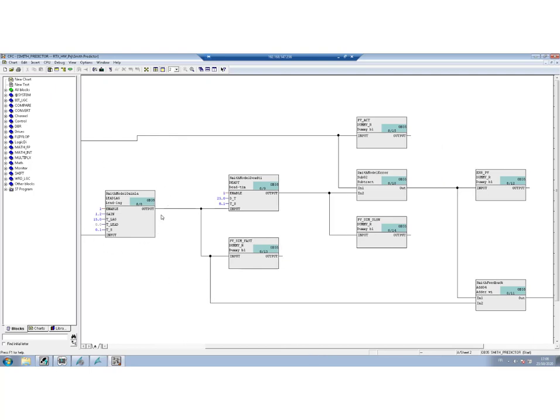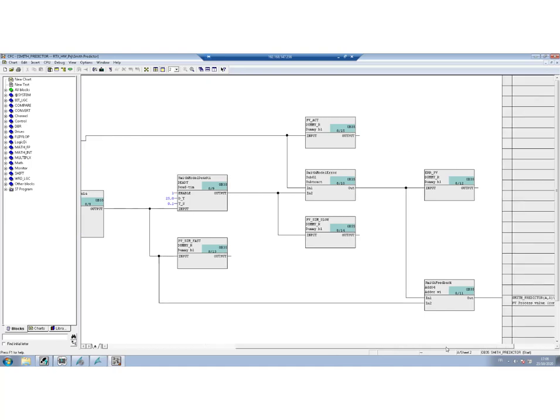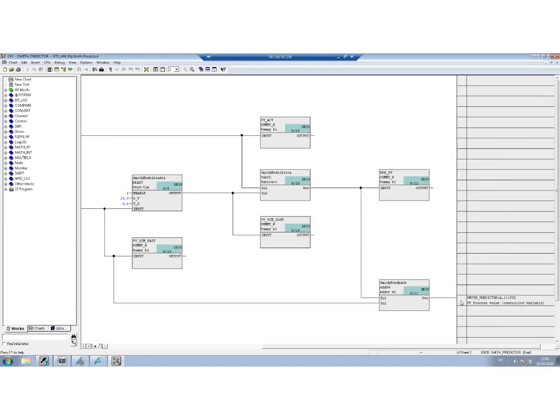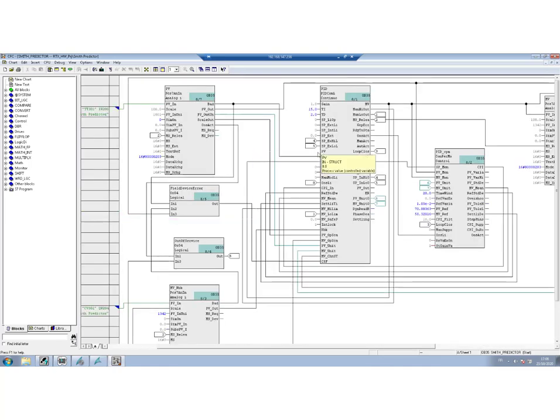So here you have the model without delay, and this is going to be added here in this adder block to the model error, right? And the model error is what is coming from PV minus what is coming out of the overall model, and the overall model is the dynamics without delay going then through the delay, right? And this predicted PV is going to the PV of the controller.